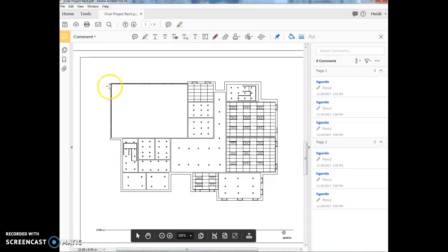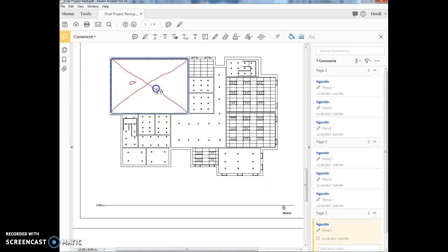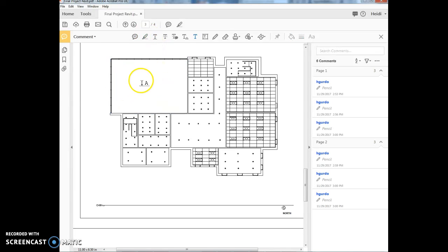In this space right here, you want to place an X, and then you want to write in all caps open. Sorry, it's really hard to, how about I type it here? We're going to write open. It doesn't seem to want to be doing it. Well, I'll just tell you because my tools aren't working quite right. We're going to write open to above. So that X indicates that this is a double story space. You put that in there and then you put text that says open to above.